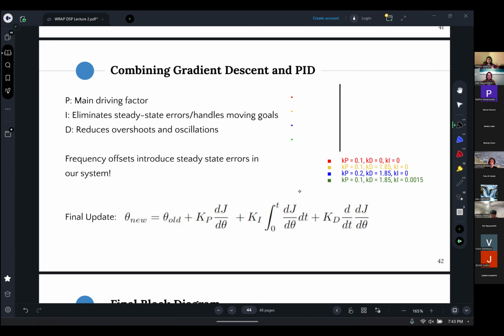And then once those are chosen, you just set them in the system and forget about it. And that's what we did in the RAP system last year. We did simulations in MATLAB to record what the data looks like, and then figured out what the optimal values for all the coefficients were, and then saved that into our microcontrollers, and then it does demodulation with the Costas loop from there.